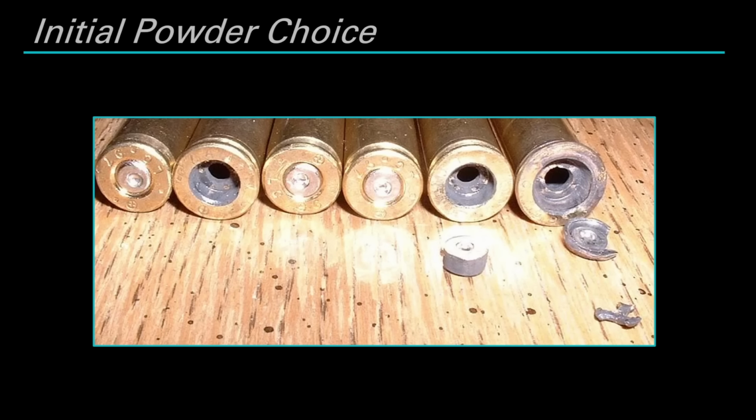And these sort of scenes wouldn't be unfamiliar to the early Army testing of the Armalite AR-15s, because 4475 loaded ammunition would be at risk of overpressure. And when we say at risk of overpressure, what we're talking about is sort of the statistical definition of risk, where some ammunition with some lots of powder are going to deviate on the slightly higher side, even with their hand-selected lots of powder, which necessarily means that eventually you're going to have some rounds that are pushing over that safe, acceptable limit, and so you're going to see primers ejected or cases start to want to fail, bulging and prolapsing, and all these sorts of issues going on.